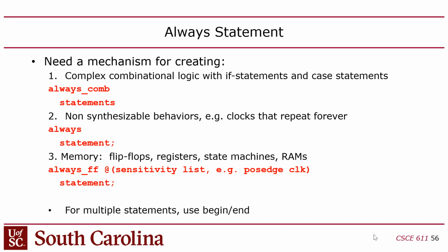But another nice thing about always is you can assign multiple outputs. And the other thing too, one final thing, the assign is creating a logic circuit. Remember how I mentioned that you can only drive an output with one logic circuit. You can only drive one signal. Any output you set in an always is owned by that always statement. So that's the logic circuit that drives it, right?